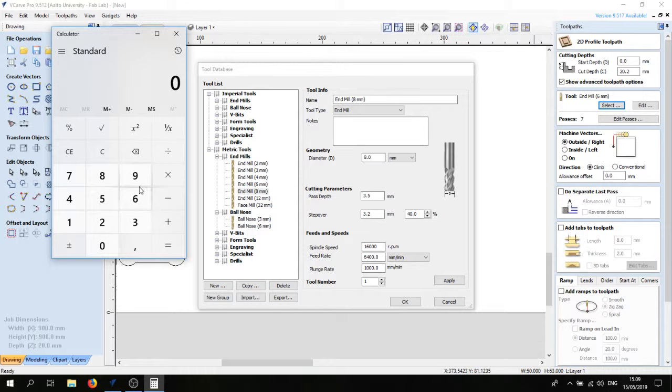You have this, but there's also a website. I need to put it somewhere so you can see. It comes from CNCRoutershop.com, and there's a section that tells you how to calculate feeds, and it has this table. We have an 8 millimeter tool, which isn't listed specifically, but we can look at a 10 millimeter tool and calculate the medium between it and the 6 millimeter tool.